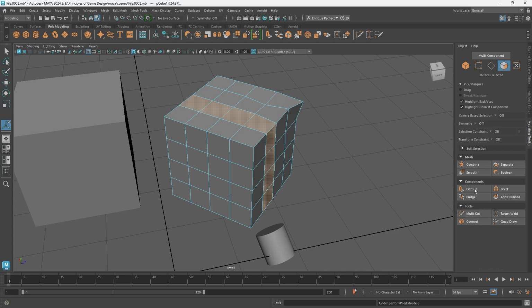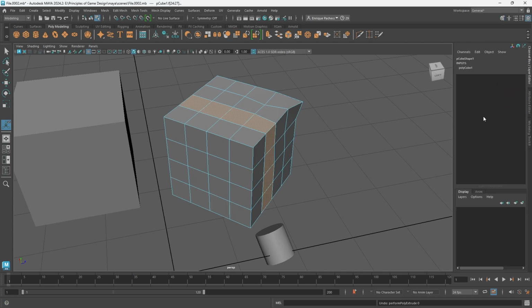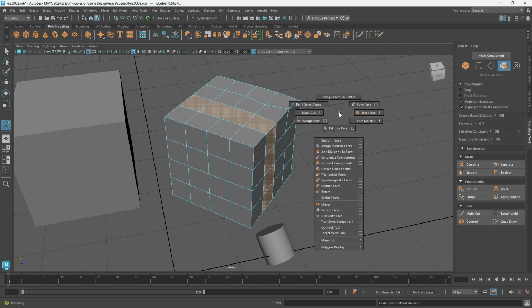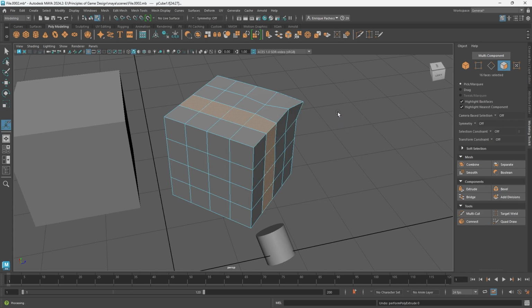You can also, if you want to keep the channel box open, use tools from the modeling toolkit up here in the Poly Modeling shelf. So for instance, that same Extrude button, we have this Extrude button, notice the picture next to it, it is the same as this picture up here, that is our Extrude. It is also the same as this picture, and that is how you can tell which one is which. Up here in our Poly Modeling shelf, now that we're talking about it, let's run through some simple examples of the tools up here.